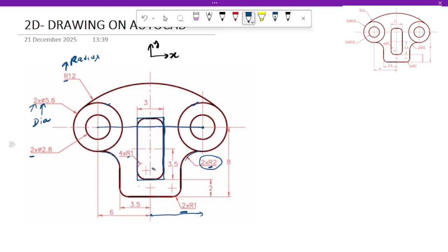And then we will draw simply this part also with a sharp corner, and similarly we use the fillet command to give a round shape at the corners. So this type of shape we are going to draw. So I'm going to start with the AutoCAD.